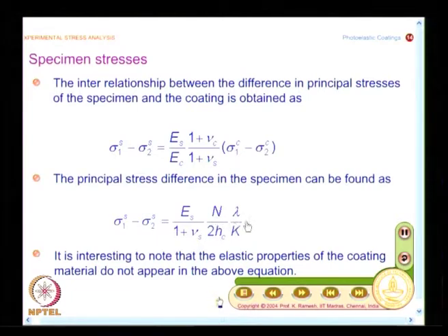Why I am reminding this is, there are certain peculiarities in reflection photoelasticity, and if you understand those peculiarities, whatever you have learnt in transmission photoelasticity, the same comfort you have in interpreting what are isoclinics, what are isochromatics. All that knowledge is the same, only the interpretation is slightly different here, and you should know the peculiarities.